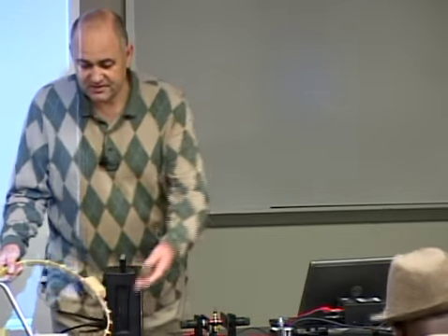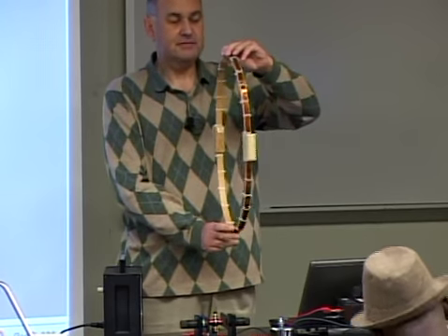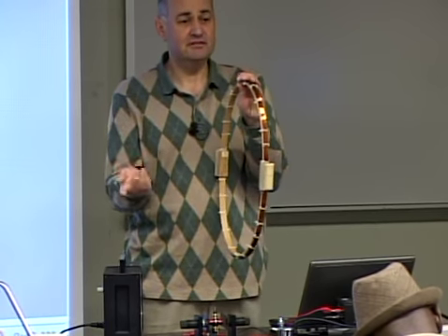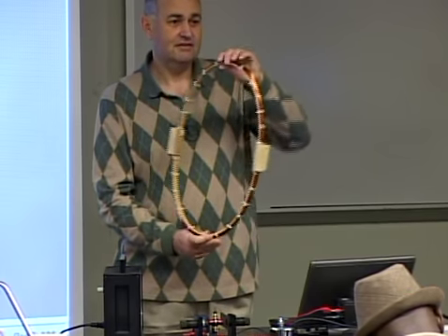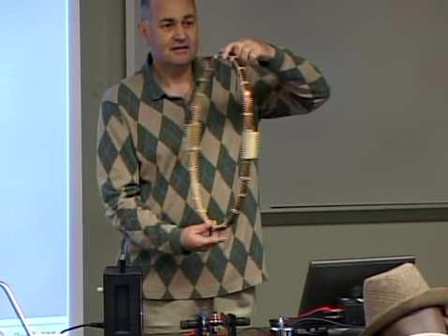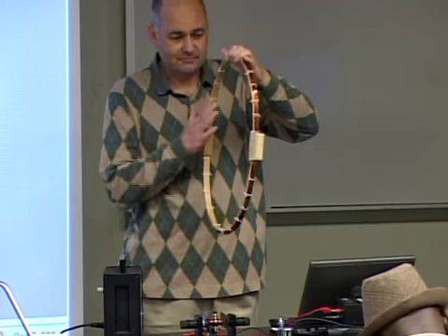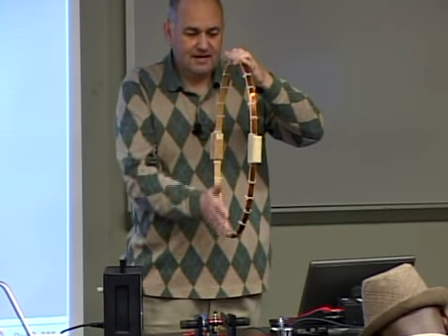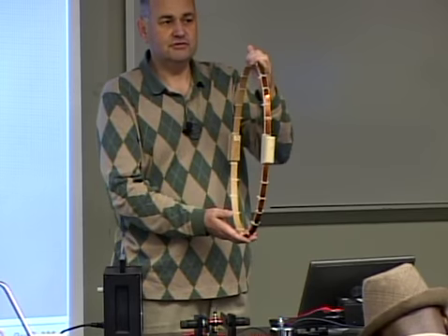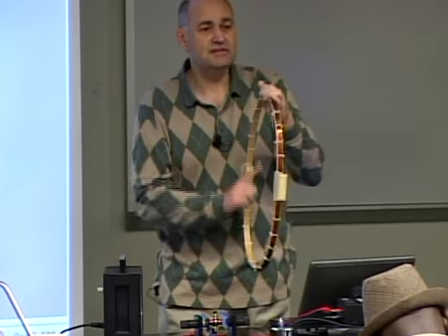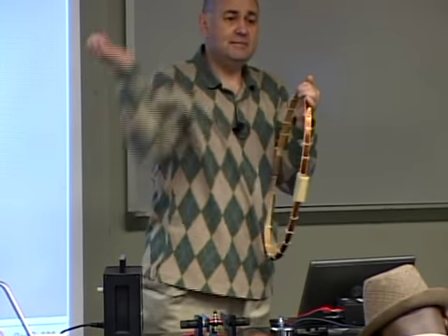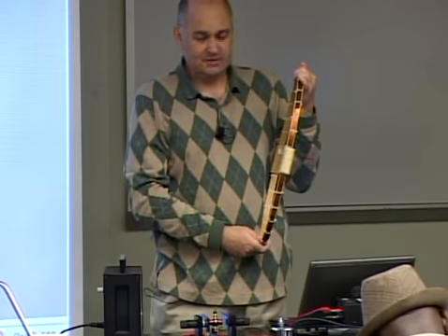Because the important thing is that in the motor, the magnetic moment flips at the right instant. As it turns, whenever the plane of that rotor or of that loop is perpendicular to magnetic field, we have to make sure that magnetic moment is opposite to the direction of the magnetic field, because then the magnetic torque will be not zero and it will be turning the loop.